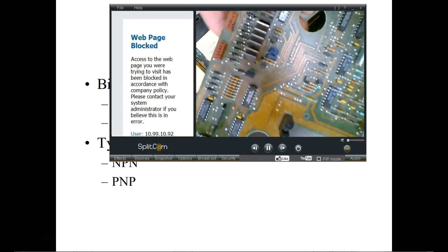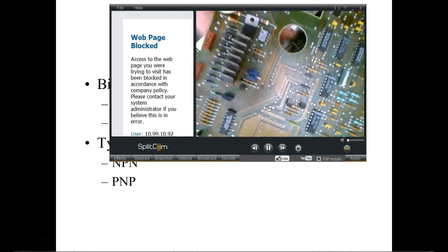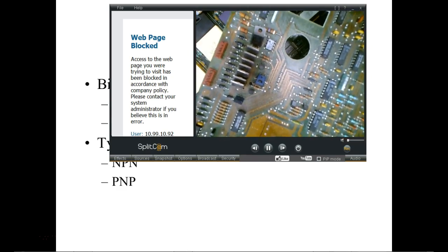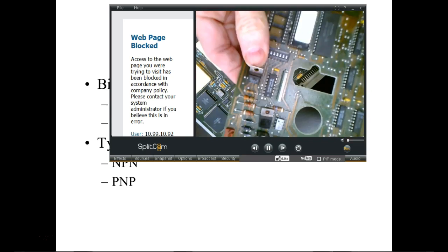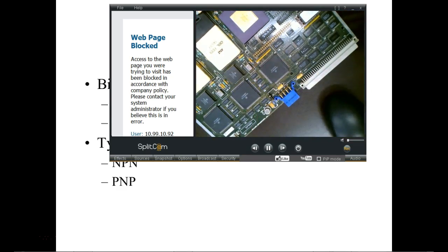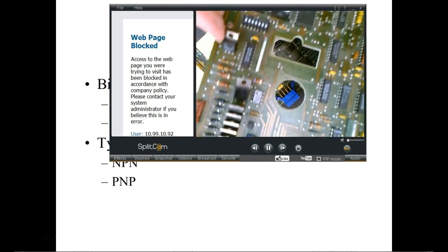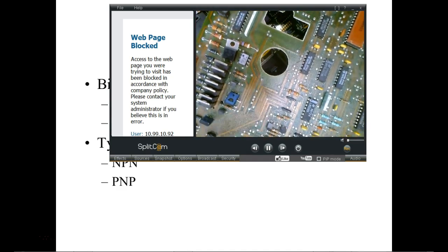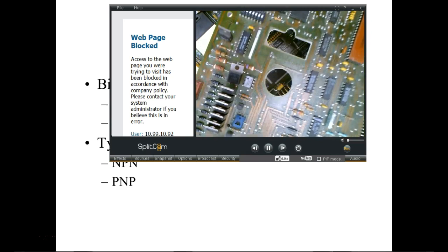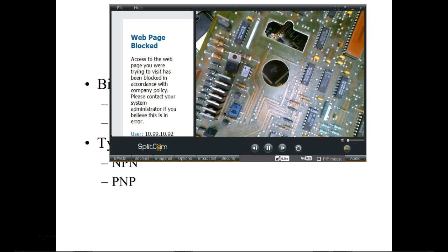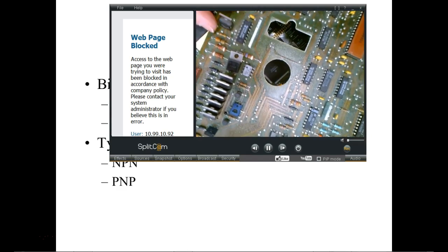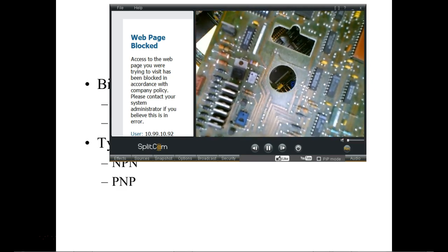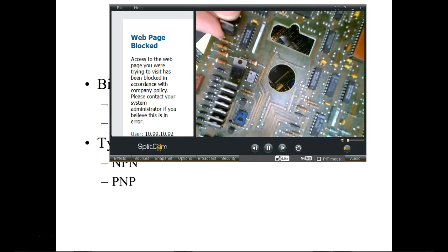These are all transistors. This we don't know. I have to look at the number, because we do put some integrated circuits inside these packages right here. These are called TO package, transistor outline package. That's just because the transistor was the first one to use that. But any circuit that only needs 3 pins will probably be in one of these packs. So we have triacs, SCRs, voltage regulators, and a lot of other circuits that use this, but we still call them a TO pack.